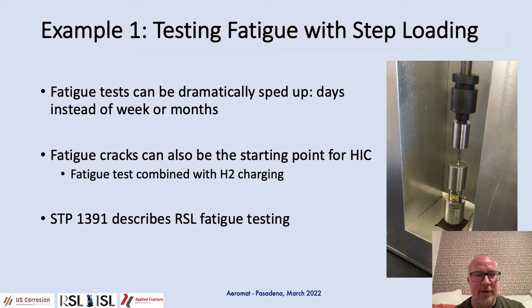And here's an example of a way that step loading has been used to speed up other types of testing, and that's perfectly applicable to failure analysis. So with traditional fatigue tests, depending on the rate and the number of cycles that are expected to be applied, it can take weeks or months to perform the tests. With step loading, you can perform the same thing, but only doing a much smaller number of cycles at each incremental step. And that means that you can rapidly determine the threshold where fatigue cracking would occur. And that can be the starting point for hydrogen-induced cracking and other things like that.